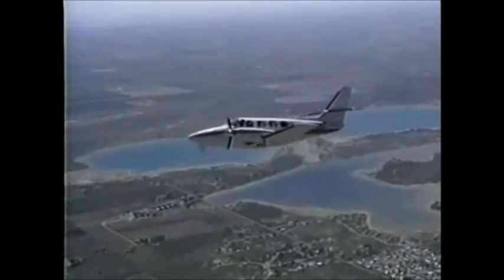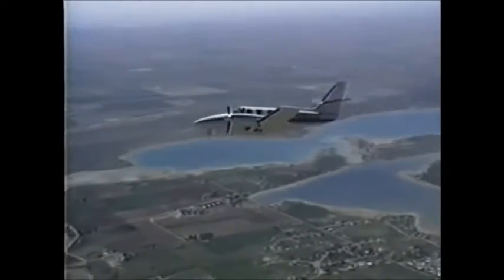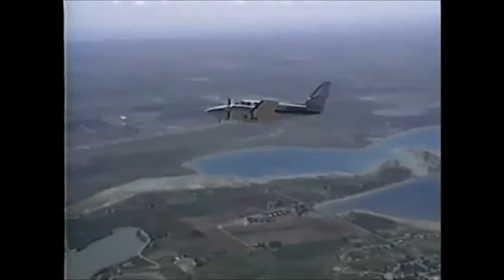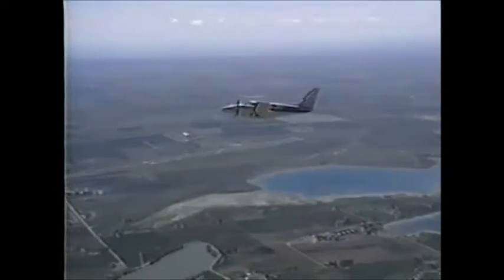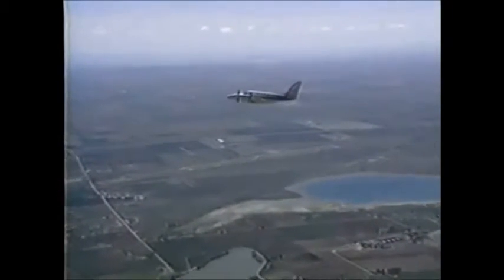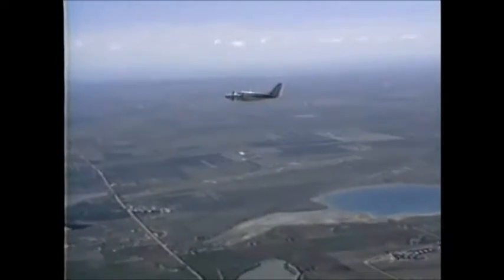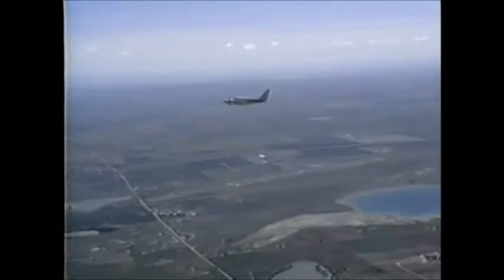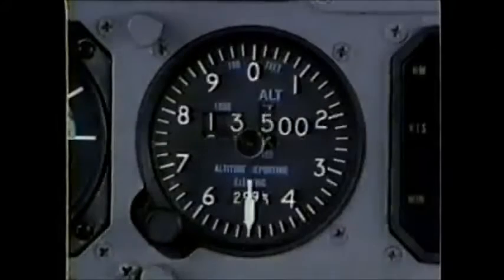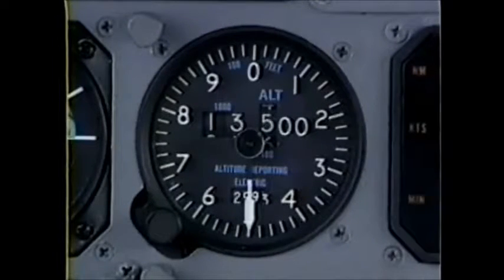If you can't restart the engine, use the checklist in your pilot's operating handbook to shut it down and feather the propeller. Once you've done all the checklist actions, you should head to the nearest suitable airport and land. Remember that the airplane will fly best if you maintain 5 degrees of bank toward the good engine and use trim to relieve the control pressures. You should maintain altitude if at all possible.